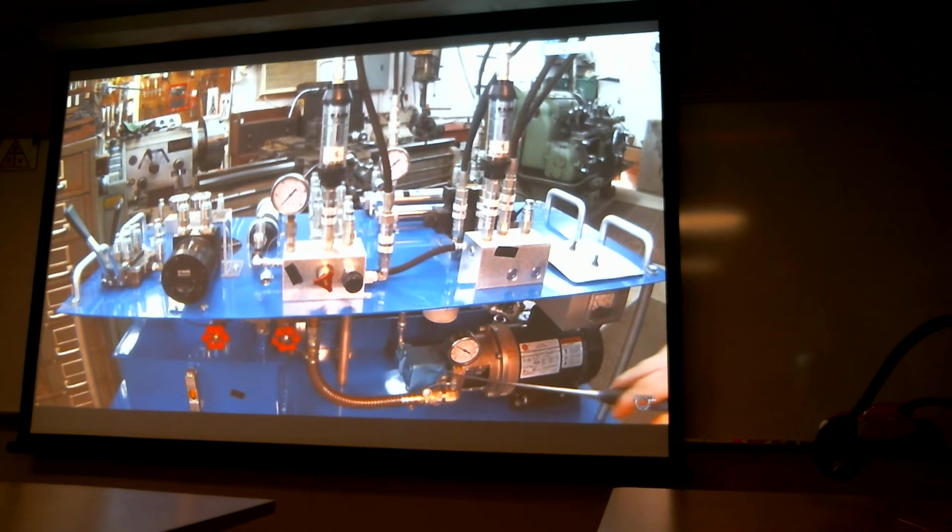Your O-rings inside of all these components right here will melt. So if you get this weird gray substance in your filters, that means that you're using the wrong kind of oil and it's melting your O-rings inside of all these devices, your sealing devices. Okay?